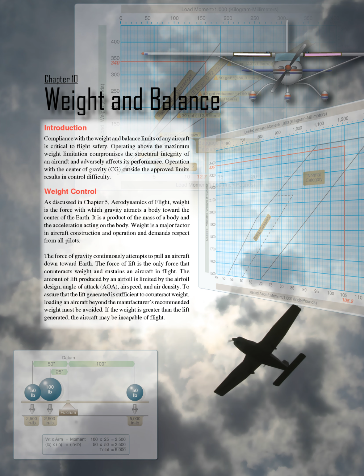The amount of lift produced by an airfoil is limited by the airfoil design, angle of attack (AOA), airspeed, and air density. To assure that the lift generated is sufficient to counteract weight, loading an aircraft beyond the manufacturer's recommended weight must be avoided. If the weight is greater than the lift generated, the aircraft may be incapable of flight.